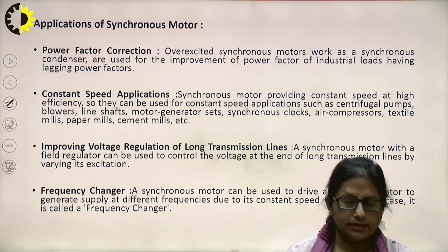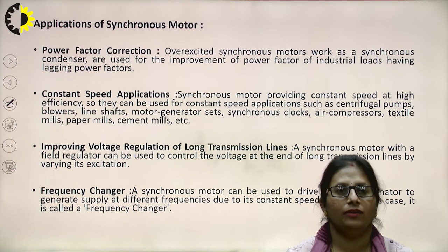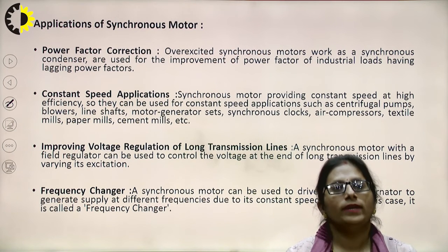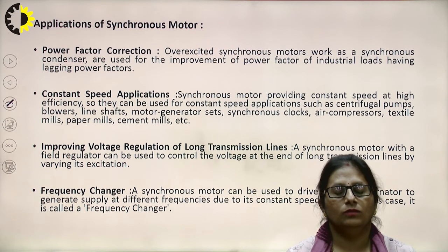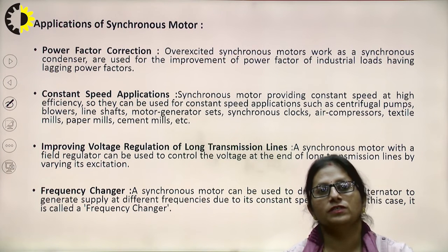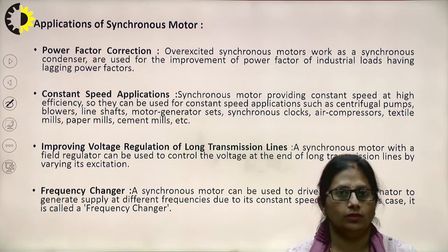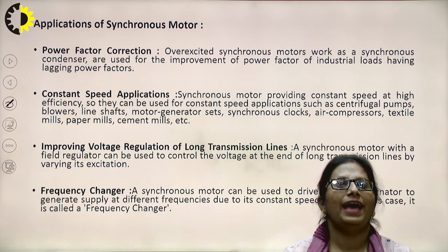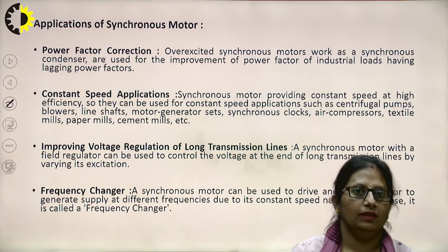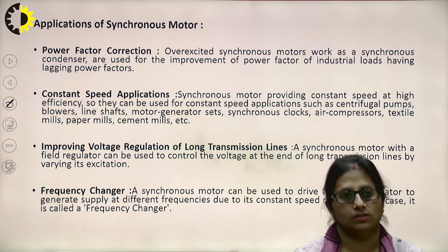The synchronous motor can work at a leading, lagging or unity power factor. When an overexcited synchronous motor is made to work, that means the excitation is given in such a way that the induced EMF is greater than the supply voltage, it is called an overexcited synchronous motor. At that state, it gives us the leading power factor and works like a synchronous condenser. That can be used for the improvement of power factor for heavy industrial loads.